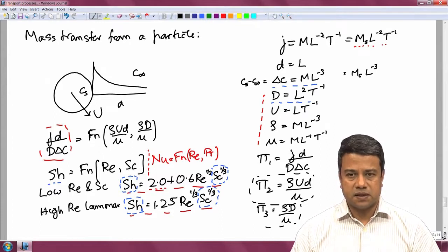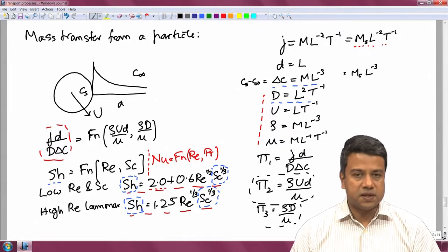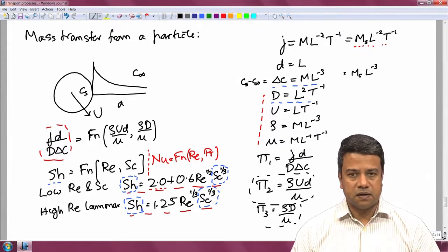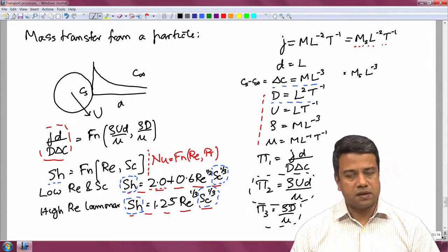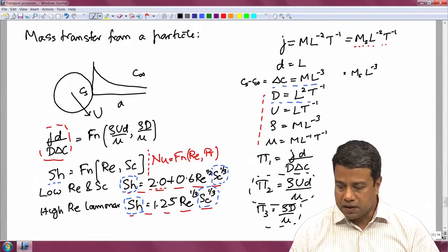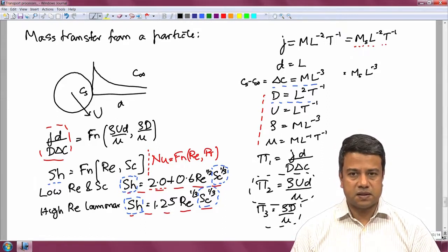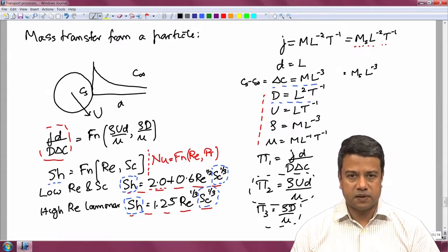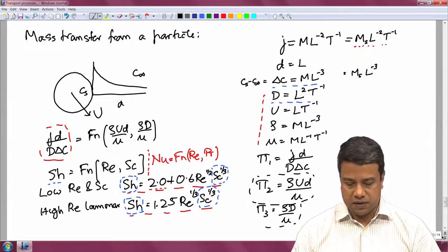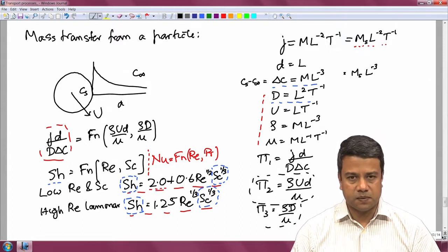In this case, mass transfer depends upon diffusion, and we had once again derived a correlation for the dependent dimensionless group that contains the average mass flux per unit surface area, as a function of other dimensionless numbers, the Reynolds number and the Schmidt number in this case.